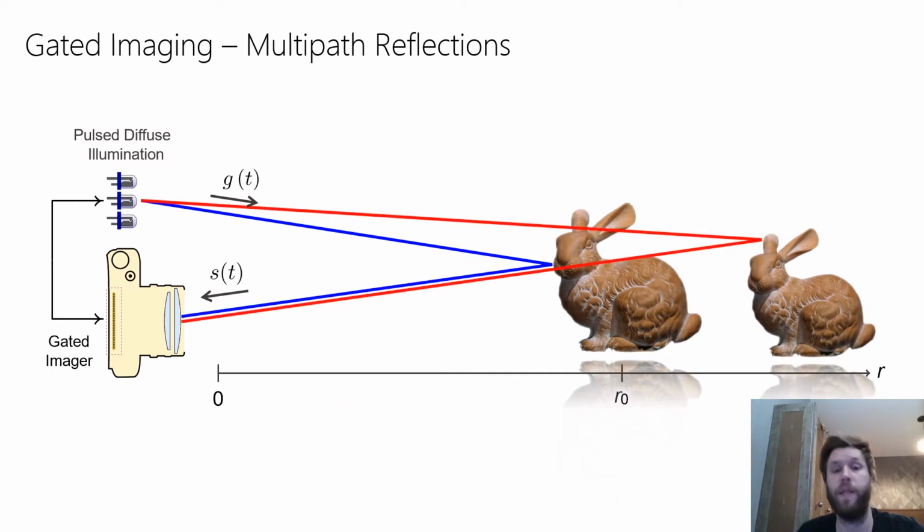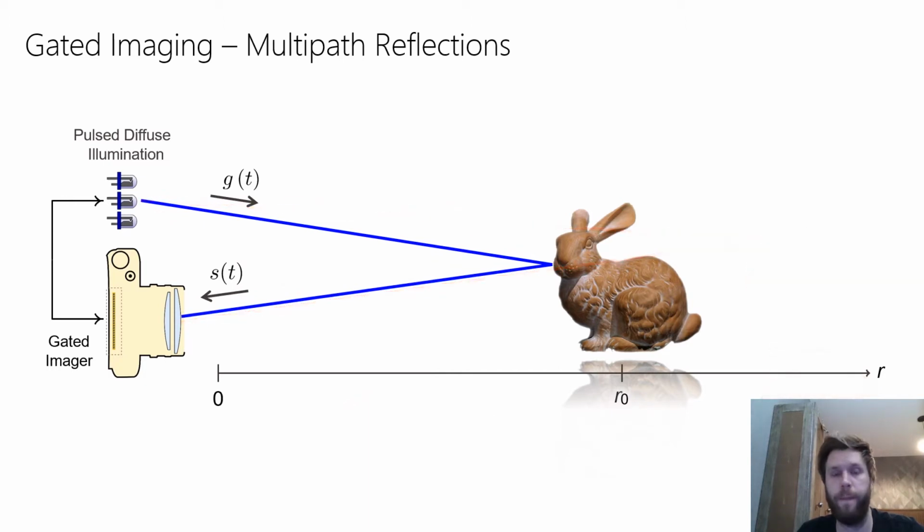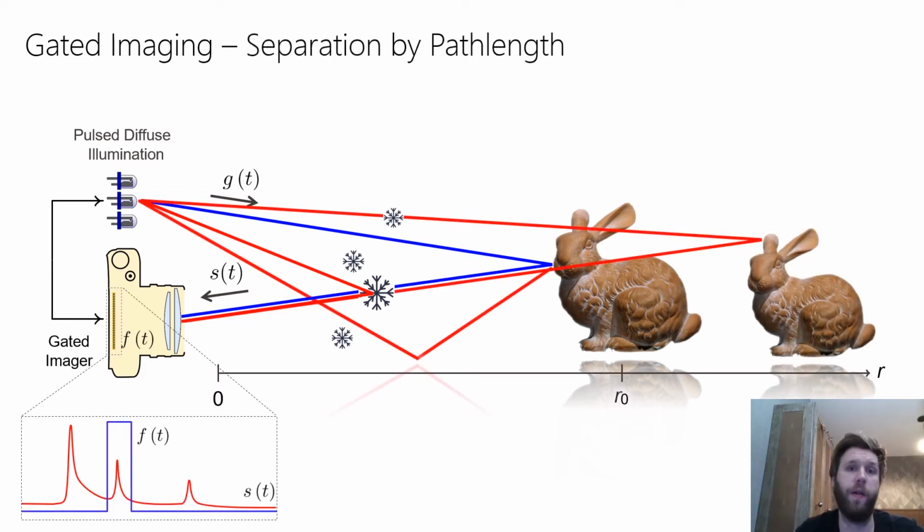or superposed from other scene surfaces, or from scattering particles in the scene, such as the example that we saw at the beginning of the few slides. So S is really the impulse response alpha here, convolved with the illumination signal G. So let's say G is a single pulse. Then S is the same impulse response alpha of the scene.